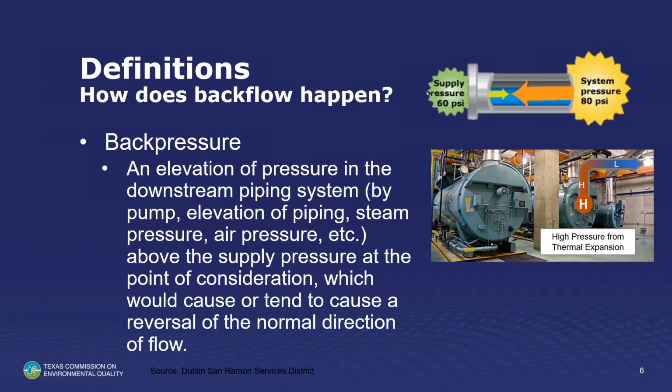Back pressure. Now, back pressure is going to usually be man-made. It's going to come from a pump or elevation, and can possibly come from a water heater, but normally it's going to come from a pump that's going to overtake that system pressure, or an elevated piping.